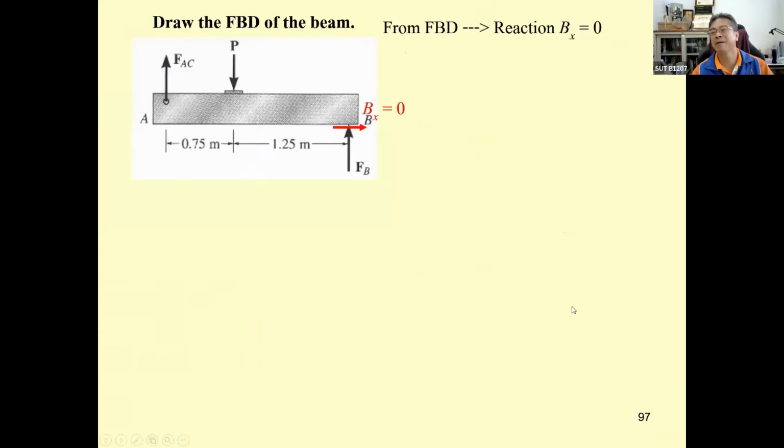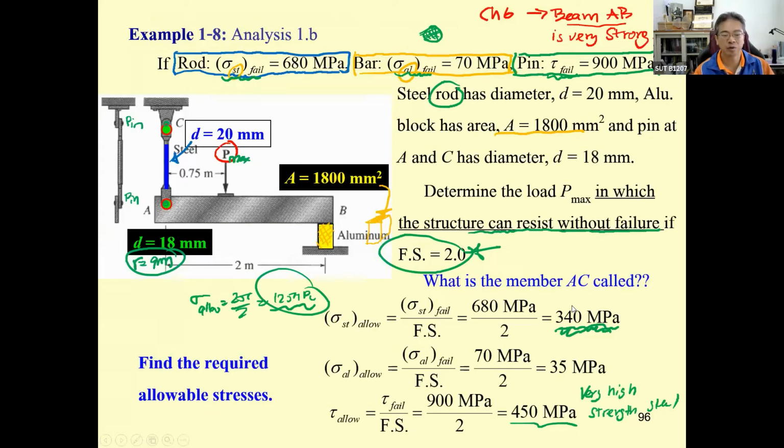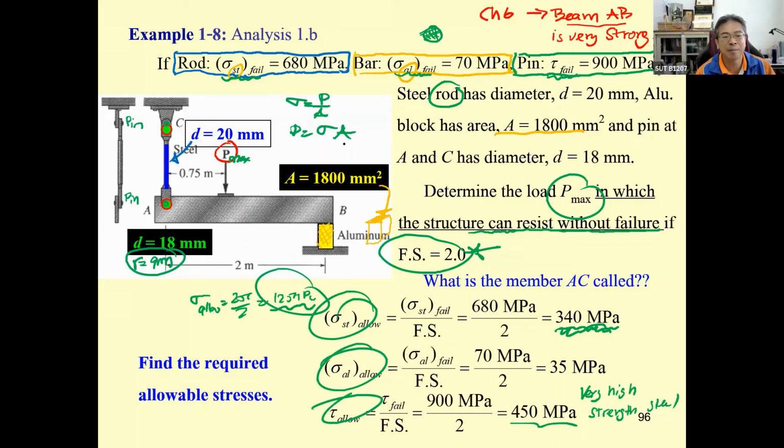Now, we have the same thing. What are we going to determine? We're going to determine the force. We have sigma equal to force divided by A, so the force is going to be sigma A. We're going to use the stress over here times the area given over here to determine each type of force. And again, this is not directly P. This is going to be the internal force that occurs in each member.